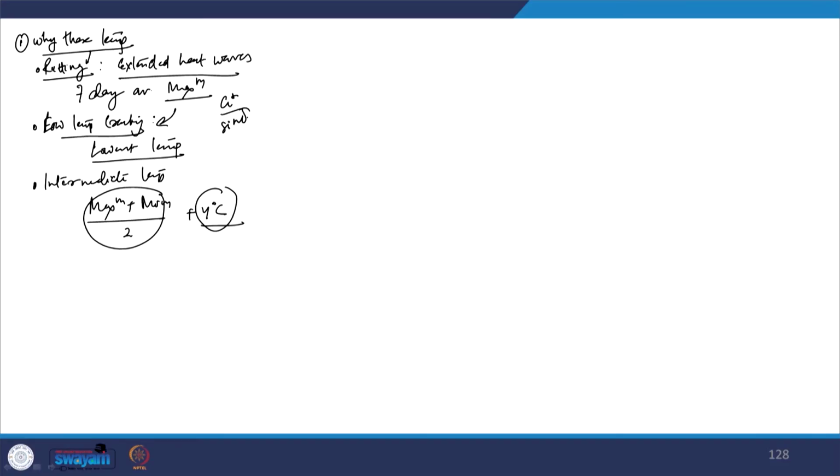Whereas, fatigue cracking is a phenomenon which will occur at intermediate temperature range and on stiff binder. The binder becomes stiff only after long term aging. Therefore, for assessing G star dot sin delta, we are using the long term aged specimen, and similarly for low temperature cracking, stiffness is one of the critical parameters and therefore PAV aged samples are used.